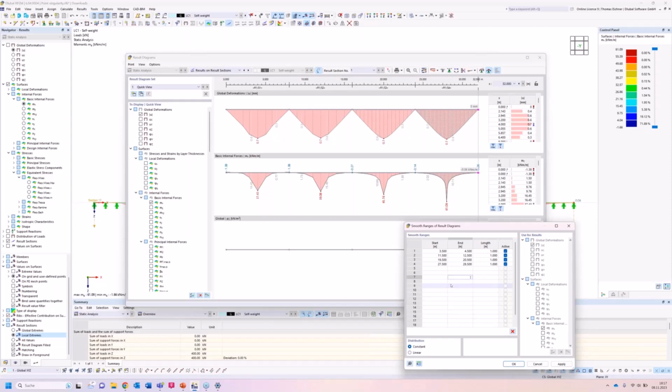So when you have a column on a slab, you firstly model it just with a point load, just because it's simple. But in reality, it stands on a square meter or 0.5 square meters, and this point load is distributed on this column section surface.